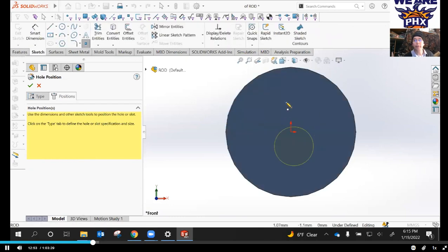Now the shape that I'm putting in here shows up. So I can just put it anywhere. That's usually, if I'm defining something, I want to not have it snap, because if it snaps, can you see the little blue line there? If it snaps, that establishes a relationship, which is something I need to delete or work around if I'm placing it somewhere besides using that relationship. So I'll just put this in a non-linear area, and now I can do more work on it.